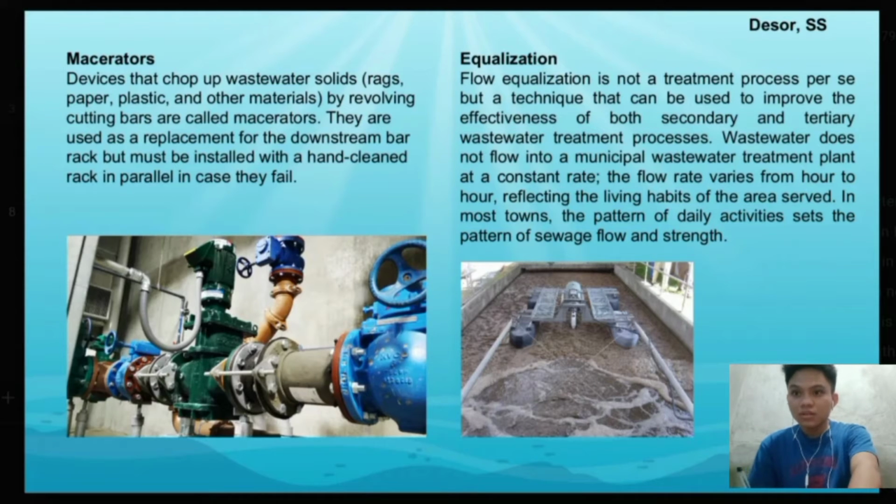The second device is the macerators, which chop up wastewater solids like rags, paper, plastics, and other materials by revolving cutting bars. The third device is equalization, or flow equalization, which is not a treatment process per se but a technique that can be used in improving the effectiveness of secondary and tertiary treatment processes.